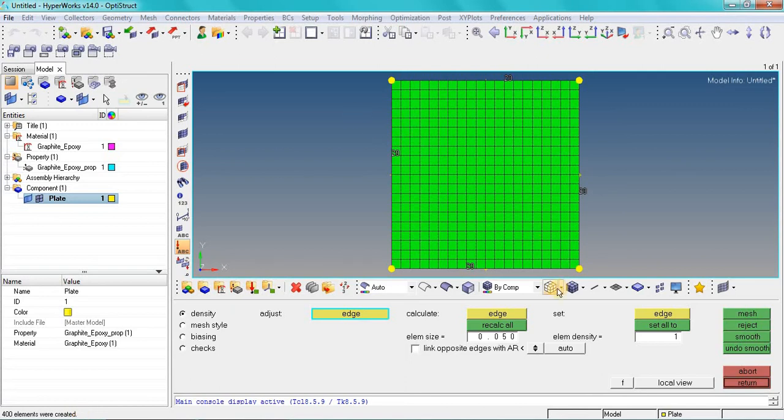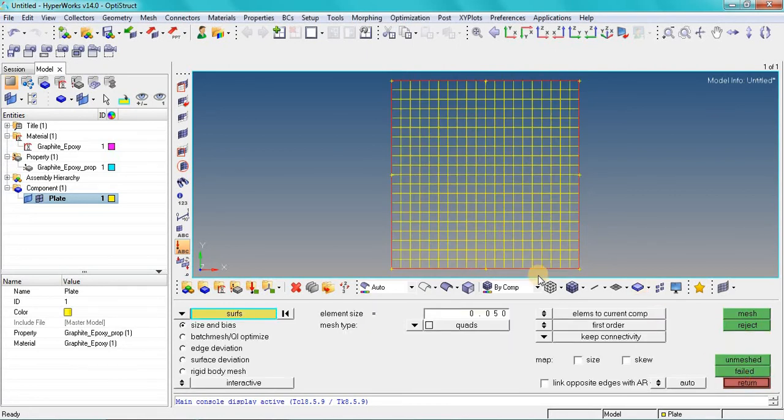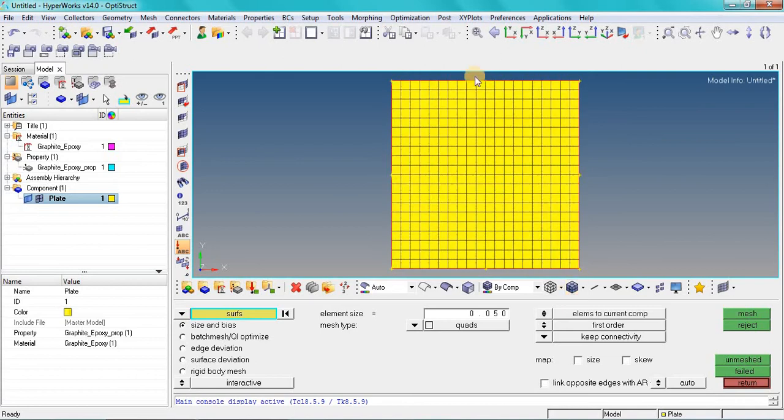Now in order to see just the mesh, you can also use the wireframe mode. So click here and choose the wireframe elements skin only. Okay, now click on this button, which is wireframe geometry. Okay, sorry, first I have to press return. Once you press return, okay, that option is visible here. So by clicking this option, yes, it becomes wireframe. Now you can click this option to see only the elements. So if you click this option, it also shows the component as well, the surface as well.